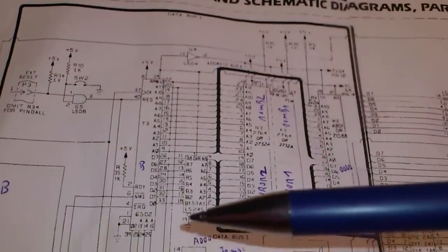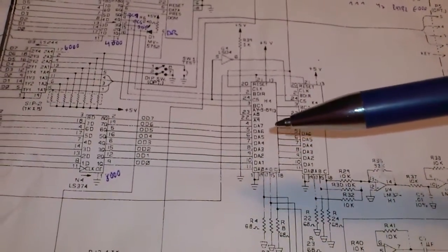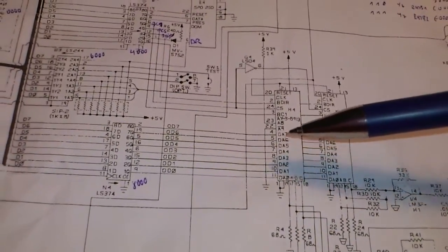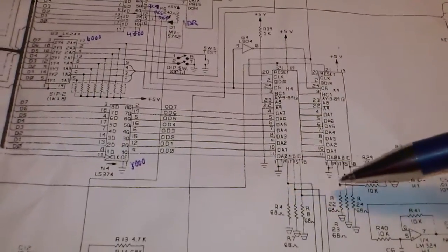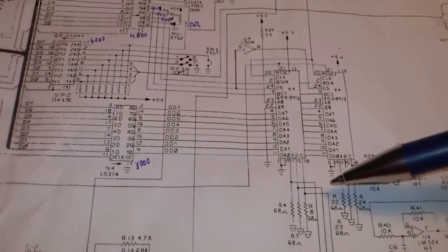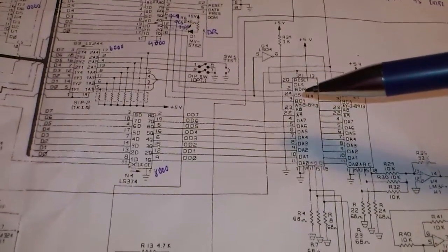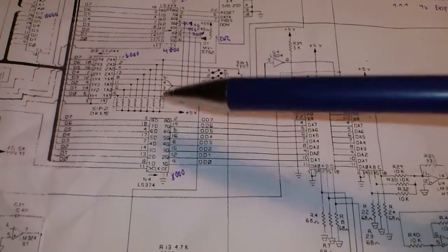Now when we look into the peripherals, we figure out that there is quite some heavy stuff sitting here. There's an AY3-8913. This is a programmable sound generator which is generating 3 channels. And there is a second one here. So in total there are 6 channels. These are the analog outputs here, 6 in total. And the CPU is writing in the different tone characteristics over those latches here. So that's the data, that's the control.